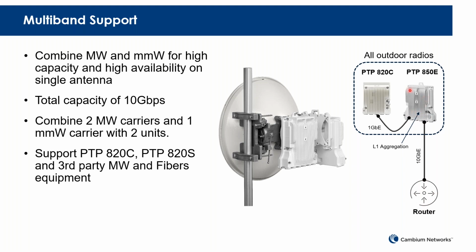In the case of our deployment, as I said, it's not a failover like almost all the products in the market. What they do is when the E-band is lost, the data will shift to the microwave. In our configuration, the E-band and the microwave data capacity is always combined. So we can support up to 10 gig capacity with aggregation. So let's see, in the case my E-band is 7 gig or 6 gig or 2 gig or 1 gig, as long as my E-band ACM kicks in, the capacity goes down.